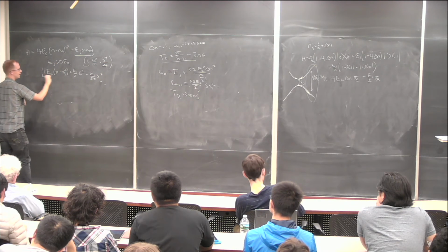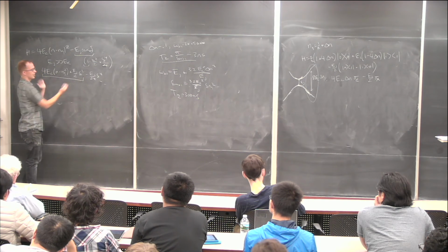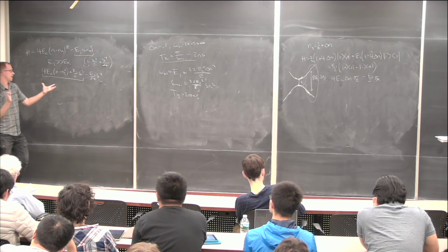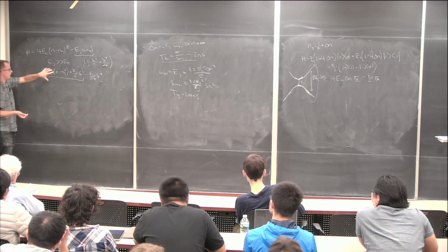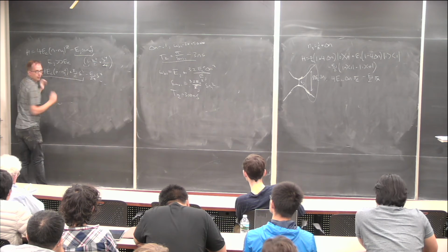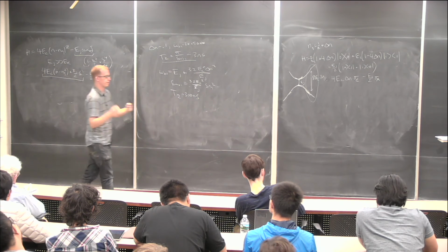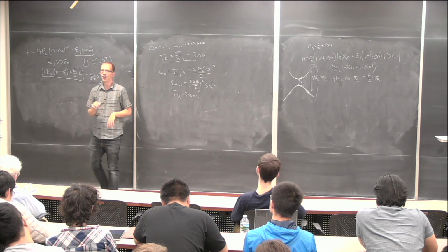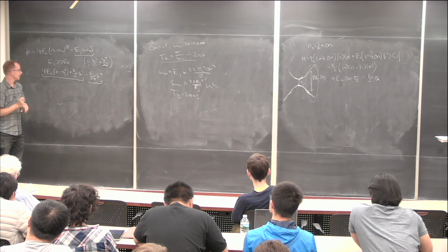And so this is really just your harmonic oscillator, right? This is an inductor term, EJ delta squared, the linear part of the inductance of the Josephson junction, and this is charge on a capacitor. If you forget about the quartic part, this is purely a harmonic oscillator again. So as you make EJ over EC very large, it looks very much like a harmonic oscillator, except you have this extra term, and this gives you an anharmonicity of exactly minus EC.